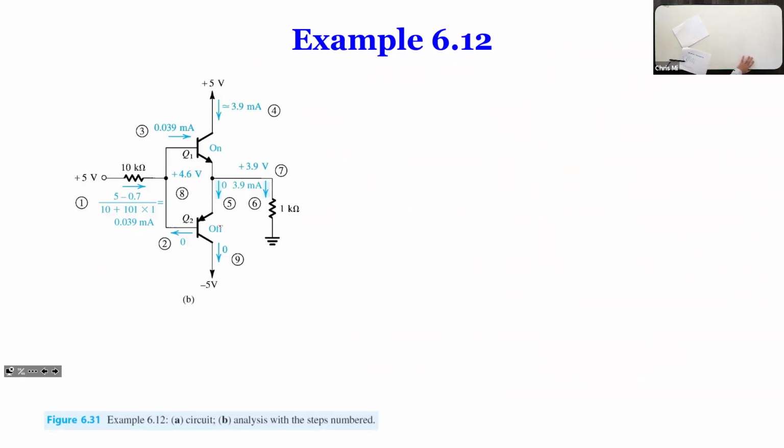Now, if the battery is not infinity, if the battery is 100, then we would have to solve for the exact value of each current and find the actual voltage at each node. It won't be too much off because this VB is very small, almost negligible, but there's still going to be some difference.